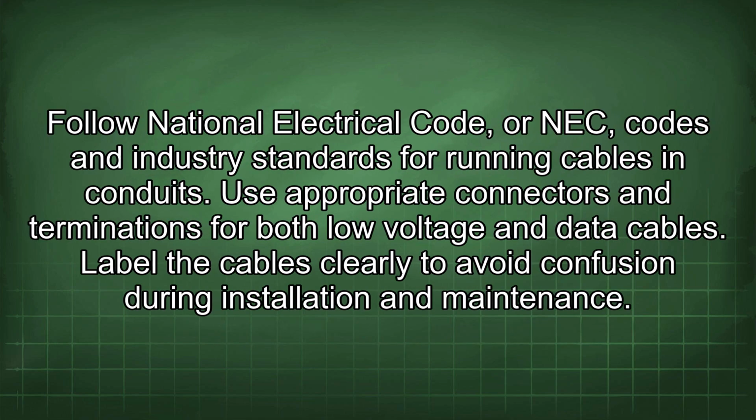Follow National Electrical Code, or NEC, codes and industry standards for running cables in conduits. Use appropriate connectors and terminations for both low voltage and data cables. Label the cables clearly to avoid confusion during installation and maintenance.